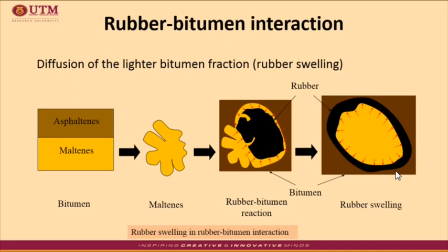It has been suggested that there is a greater degree of rubber-bitumen interaction with greater enhanced properties in the wet process than the dry process, thereby making the wet process the preferred method of modification. The rubber-bitumen interaction in the wet process is well established as it is considered a major reaction that occurs within the mixture.